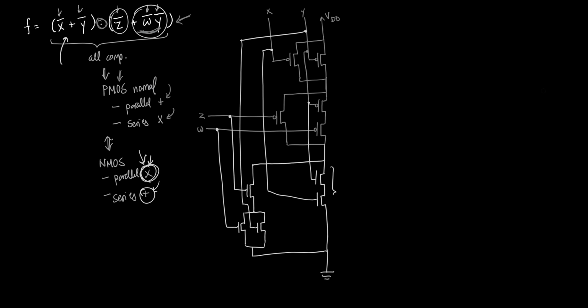So here we've got our X plus Y because they're in series with each other. Here we've got this big part in series. We've got our W times Y because those are in parallel. We've got our Z in series with it to add to it. So here we've got our Z plus WY, that whole part there. And then this entire thing, since this half is in parallel with this half, it accomplishes the big multiplication in the middle. So now that we've completed the CMOS gate, we can start taking a look at our output.